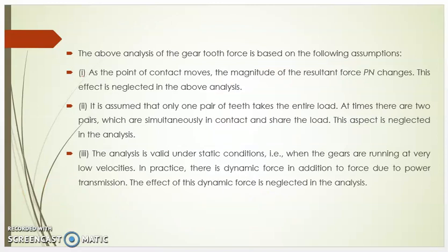The above analysis of the gear tooth force is based on the following assumptions. First, as the point of contact moves, the magnitude of resultant force Pn changes. This effect is neglected in the above analysis. Second, it is assumed that only one pair of teeth takes the entire load. At times there are two pairs which are simultaneously in contact and share the load. This aspect is neglected in the analysis.